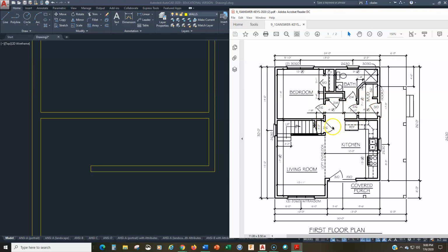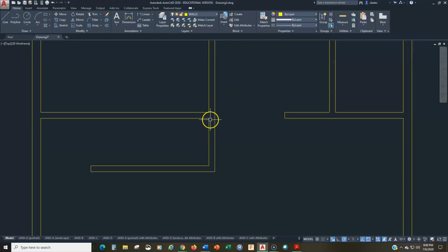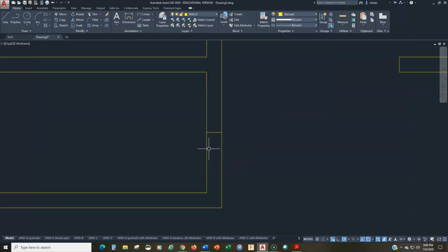Okay, so the 2 foot 6 inch door is going to be centered in this wall. So centered along this wall right here. What I'm going to do to draw this is use my object snap midpoint, and I'm going to draw like this. Now the door, so that line is in the midpoint of this wall right there.